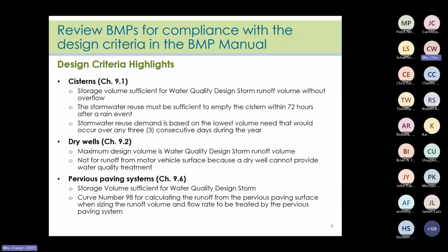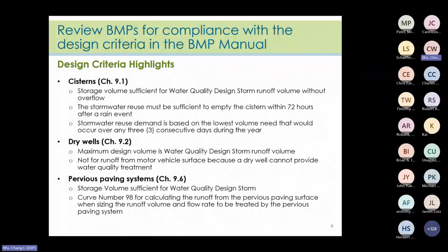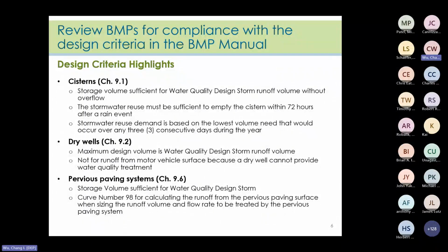For a dry well, the maximum design volume is the water quality design storm runoff volume, and it is not for the runoff from motor vehicle service, because the dry well cannot provide water quality treatment.